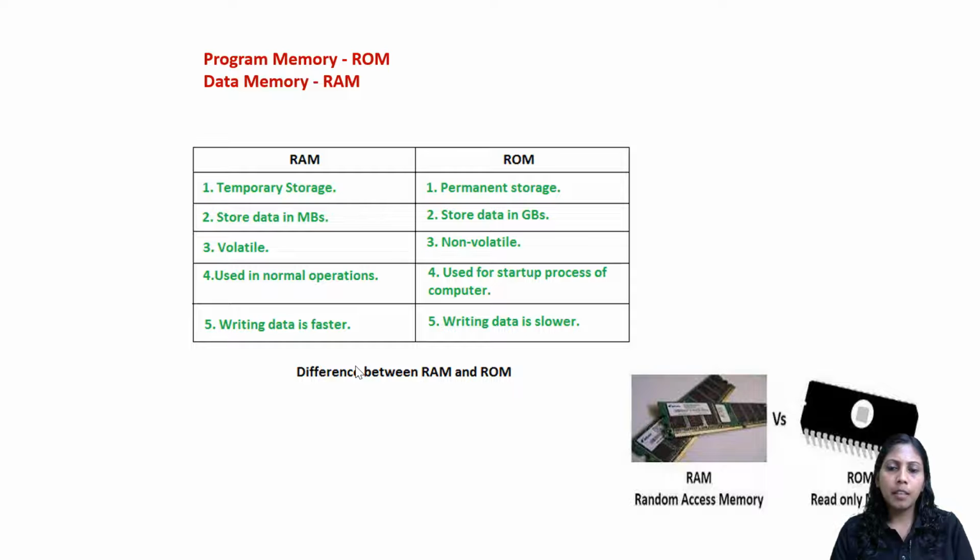In RAM, we can do the normal operations. That means even while an embedded application is running, the application can generate some data, and we can store this data in the RAM. So we can edit it even at runtime. On the other hand, for ROM, as I told, it's not possible. Once I add the code into the ROM space of the controller, it becomes permanent there.